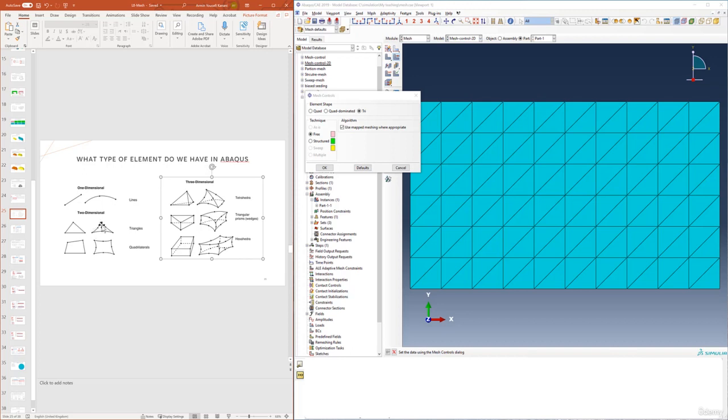Similar to this one. So as you can see, if I have a curvature here, I definitely need the point in the middle. And if I don't have that point, then that will transfer to a straight line. So depending on the geometry, sometimes it's important to have a node between two nodes. But generally, the default in triangle, in 2D, you have 3 nodes.